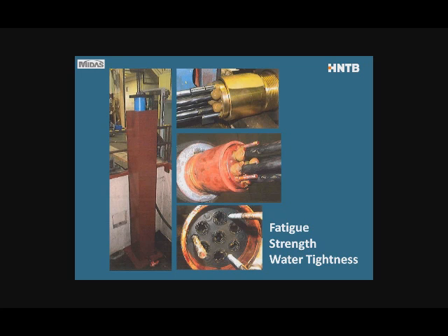and then after the fatigue test, one of the cables is stressed to failure, and another one is submerged in 10 feet of water with dye in it. And it's nasty stuff. You can see it in the 3 pictures on the right hand side. And it has to sit there for several days, and then after several days the anchorage is disassembled, and in order for the test to pass, none of that dye can reach the strands. You can see that in the bottom right hand picture where you see the openings for the strand, but the dye has not penetrated. This is, by the way, the test that was confirmed for the Lake Champlain Bridge.